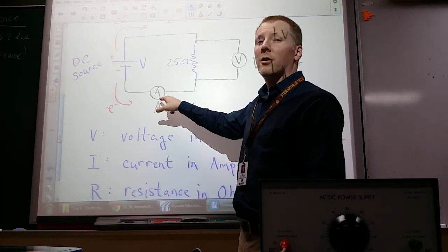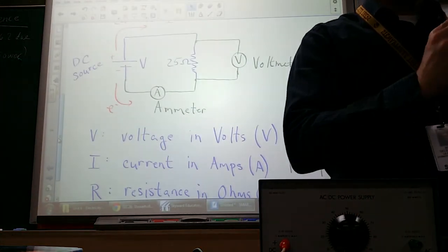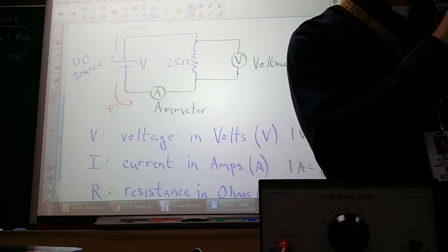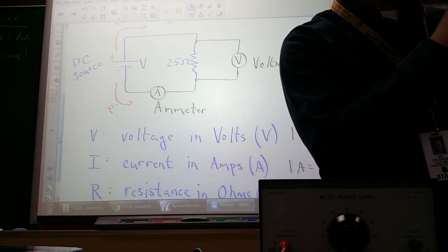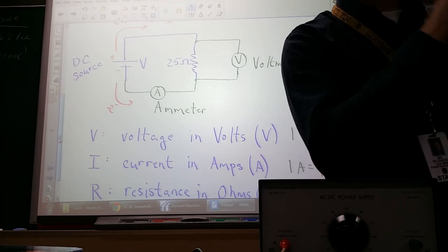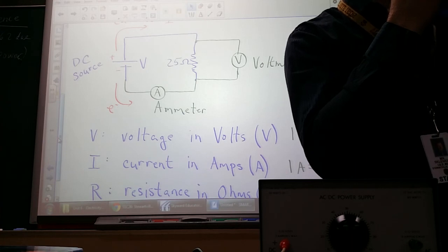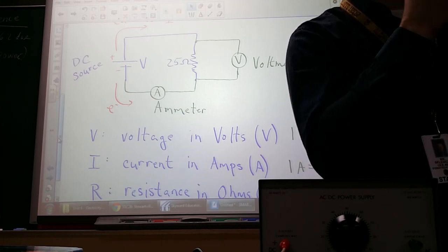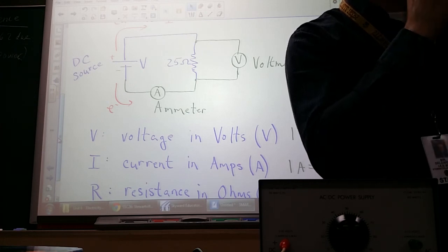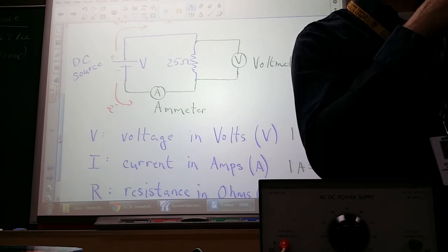We also want to measure the current using an ammeter. So I only have this one left, so I'll have to take it off. There are 2 ports for current. Most of these have, you notice that it says 200 milliamp max fused between the common and the middle, the mA. There's a small fuse inside here that gets blown if a student, say, hooks it up and puts too much current through. The ones with the little sticker that have mA on them are the only ones that still have that fuse intact. For a while I was replacing them, and then I just got tired of it and stopped. That will still work fine for us. If you happen to have an mA on there, you certainly can use the milliamp port. Just keep in mind that if you're approaching 200 milliamps, you need to swap it out.